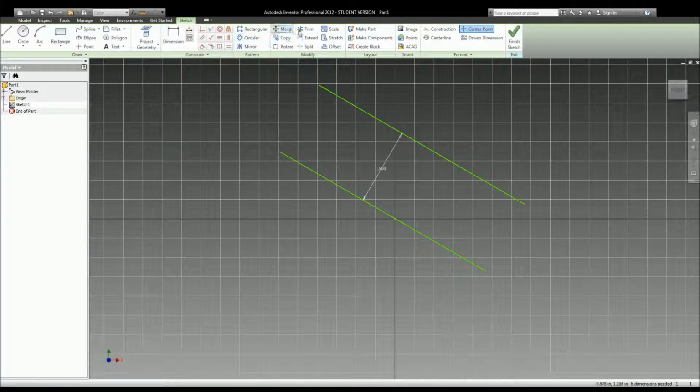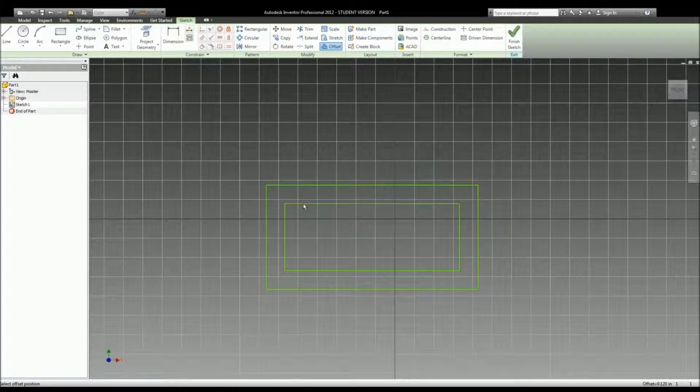Let me go ahead and go over this function again, but with a shape. So let's go with a rectangle. All right, escape, offset. I'm going to offset this rectangle. And you see how it's different? The offset for an actual solid shape is kind of a thickness to a box, for example. So say the original one is the outside measurement of a square bar, okay?